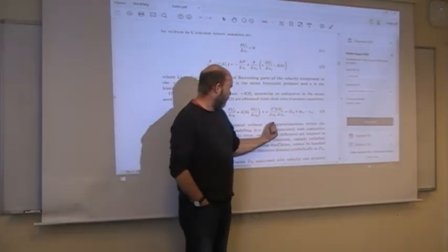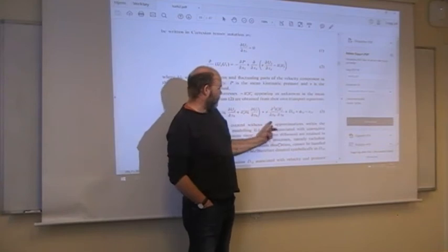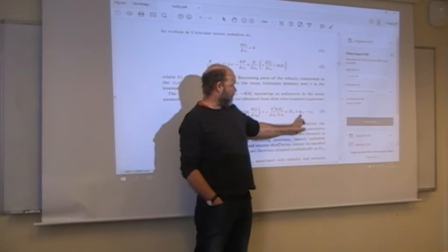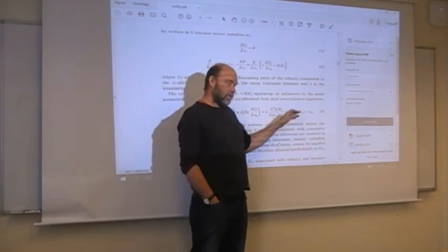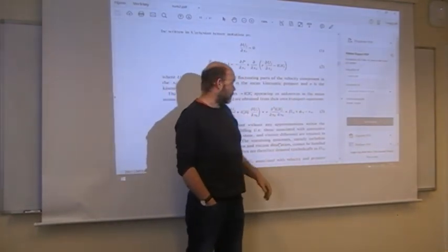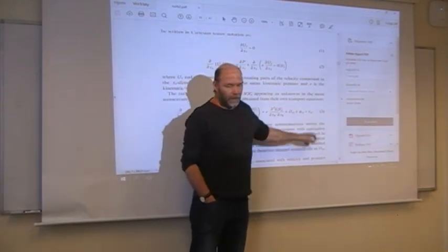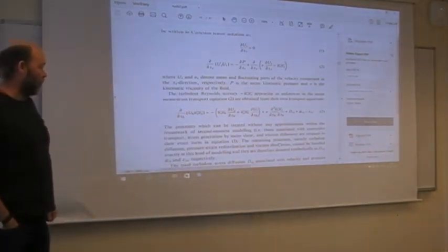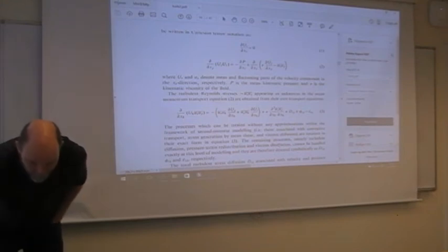But here, when we talk about diffusion terms, they have to be modeled, and then the pressure strain term, the redistribution term, the one that took energy from one component of the Reynolds stresses and gave it to one of the others. These have to be modeled. And finally, the dissipation, well, there we use a transport equation of its own, like in K epsilon. So it's a transport equation for epsilon.